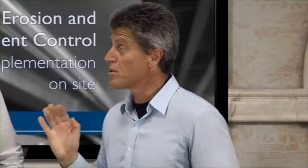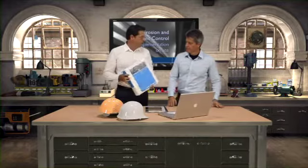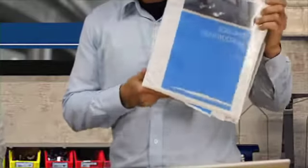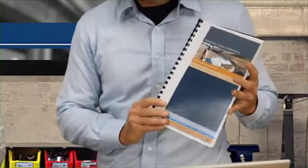Now, Chris, if people are interested in more information or advice about erosion and sediment control on RMS construction sites, where do they go? What we've got is what we commonly call the Blue Book. This is essentially the New South Wales Bible for erosion and sediment control. The Blue Book is a very comprehensive overarching document that covers every aspect of erosion and sediment control. There's generic information in Volume 1, and there's also road-specific information which is contained in Volume 2D. Also, RMS have an erosion sediment management procedure that is used to identify high-risk sites in the planning phase.